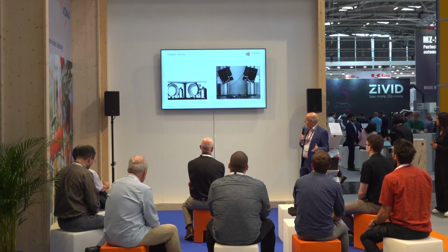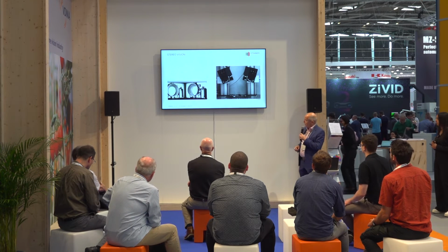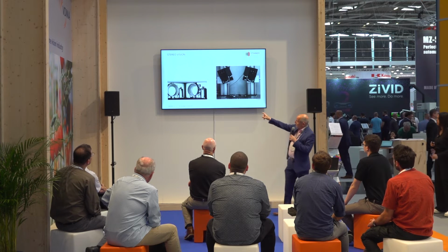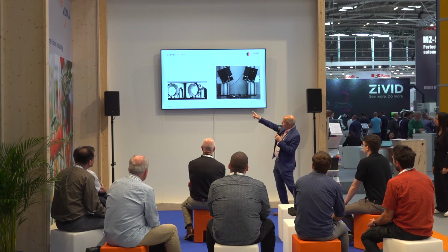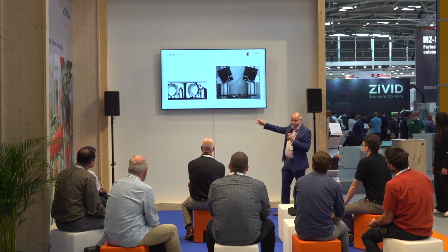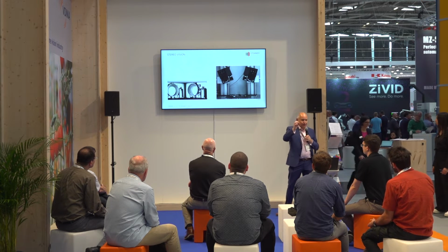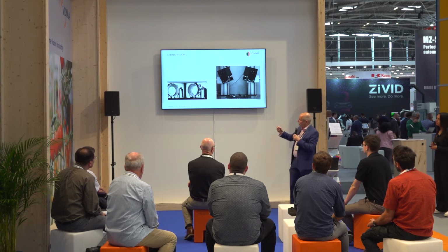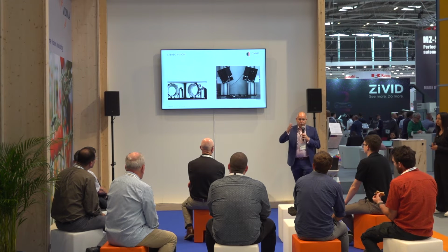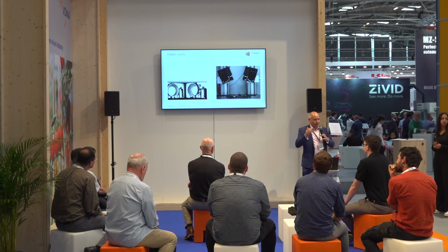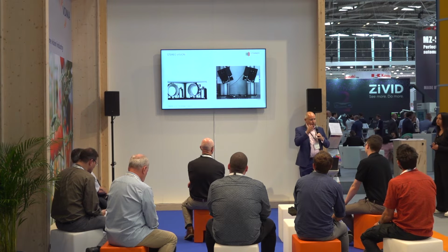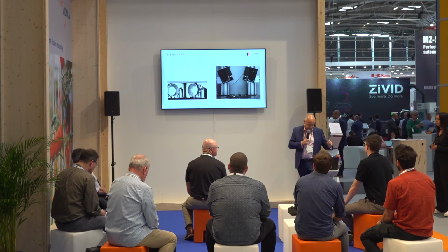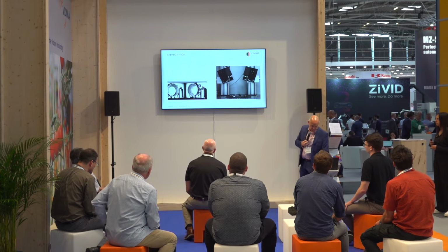So this is a typical configuration, 2 cameras looking down at a part. What you also find is, because of depending how sharp the angle is, you will get occlusions. Camera 1 is only seeing one side, but it doesn't see the other side. So this is the first thing that's going to come in. You'll see this being repeated in many 3D applications. It's what we call occlusions. As soon as you're using stereo, you have the risk of occlusions where one of the angles can't see the other. You can't get 3D data at that point, and there are ways around that I will discuss later. So that's a typical setup with the problem.